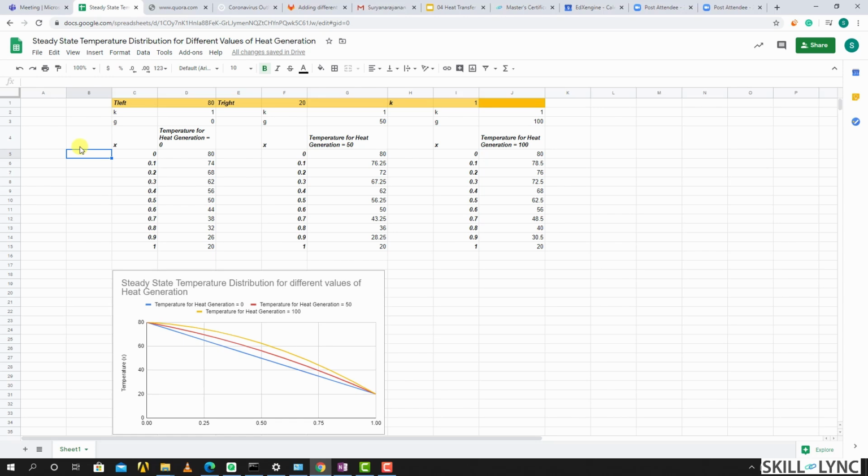Alright, let me summarize what we learned in this particular lesson. We looked at how to derive an energy balance equation for a one-dimensional problem, and we looked at the derivation with and without heat transfer. Though we did a one-dimensional analysis, this actually teaches us a lot about batteries. If you want to compute the temperature distribution inside a battery accurately, you just have to get the heat generation term accurately. Once you do that, you can use this particular equation to get the temperature distribution inside the single cell that you have.